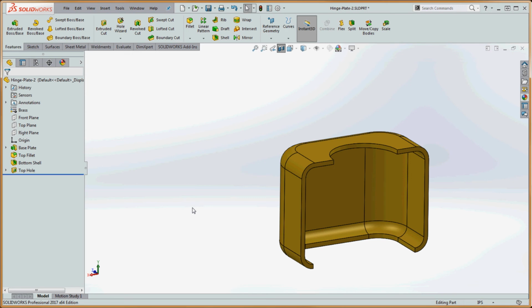This gives you an opportunity to play around with those errors and try to correct those errors and try to understand these errors. And as you're putting your model together, you might want to avoid these errors, know how to fix them when you get there, but you certainly don't want to have errors propagating through your model because it'll make your model unstable, which will make SolidWorks unstable. So get good, solid modeling geometry down from the very beginning. Start with your sketch. Make sure it's all well defined. If it's going to be well defined, ultimately do it from the very beginning and make sure your features are nice and tight and proper where they should be.